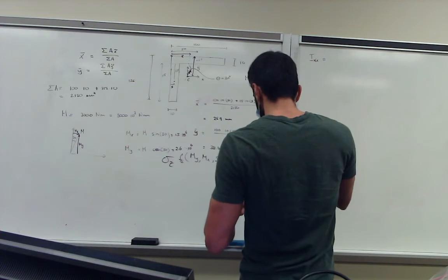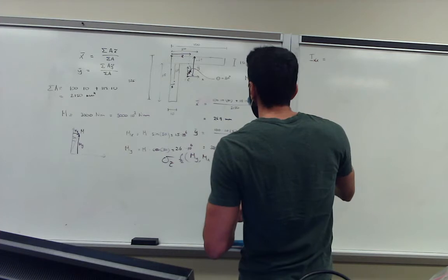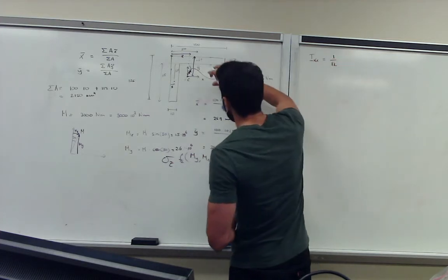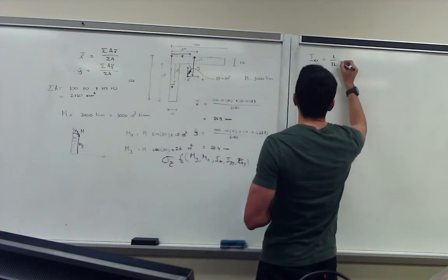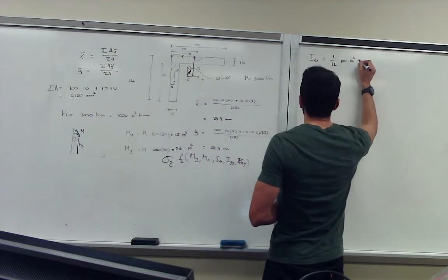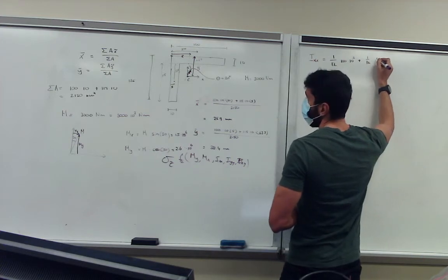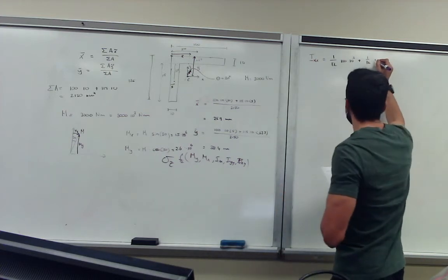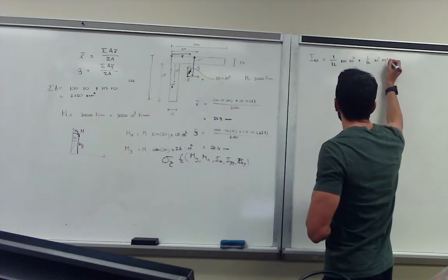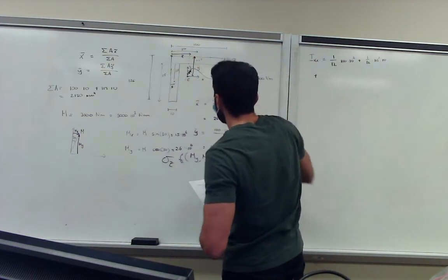In this case, we assume it's going to be thick-walled, so we take everything into account. So we get the top part, that's basically 1/12 times 100 times 10 to the power 3, plus this part, we get 1/12 times 115 to the power 3 times 10, and then we add the standard terms for both parts, because we have to translate it with respect to the coordinates.